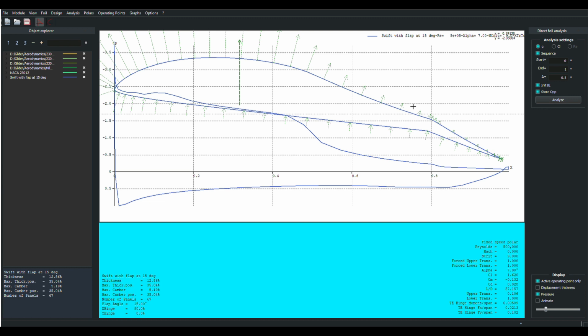So what's the best way to answer this problem, to design these gliders? Well, my current answer is almost flat plate. Because to have most of the pressure recovery done by the time you get to this hinge point, you have to have one of these rooftop pressure recovery type airfoils, which has this type of upper surface on it, and they're just inherently going to be very draggy at higher speeds because flow begins to separate.